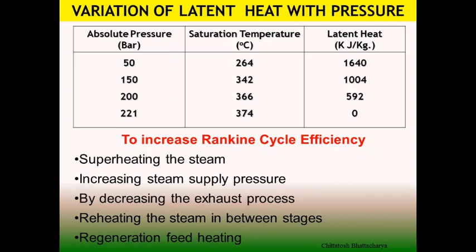1640 kilojoule per kg, and if we go on increasing the pressure to 200 bar, then saturation temperature comes to 366 degrees centigrade, and the latent heat of vaporization that is required reduces to 592 kilojoule per kg.